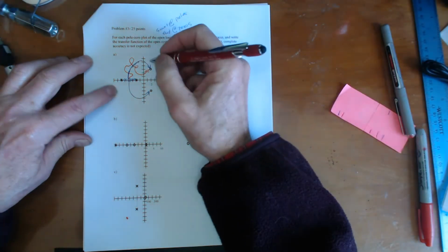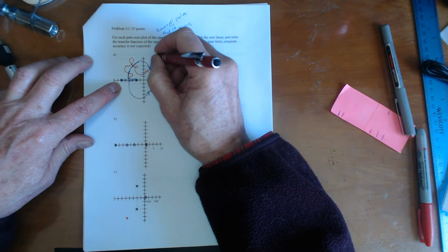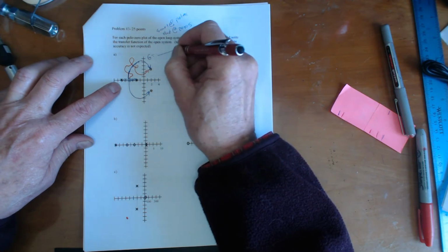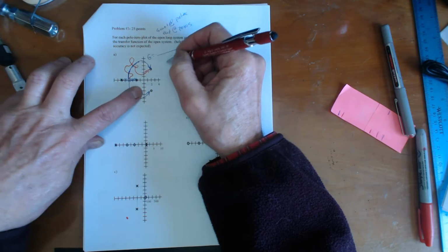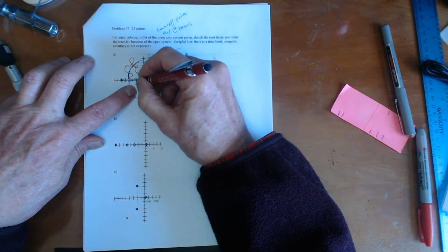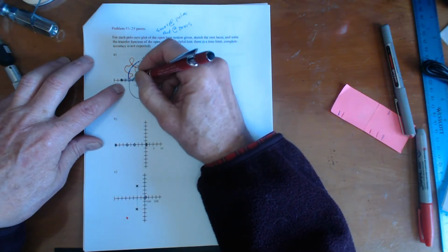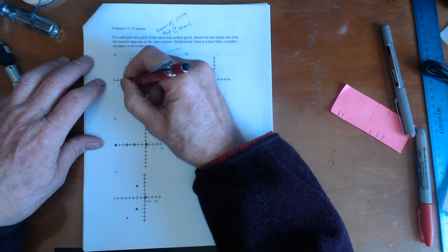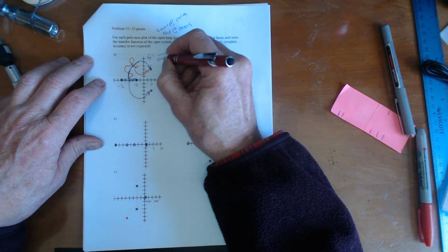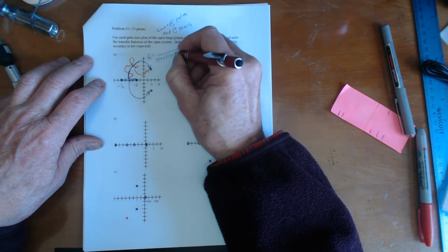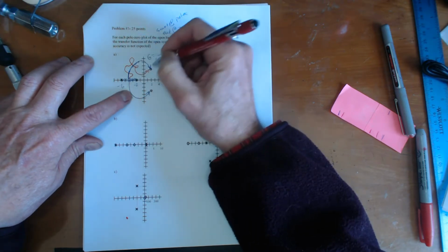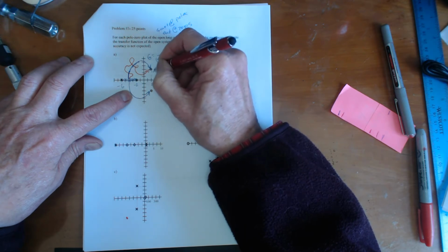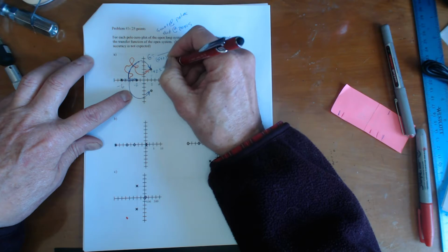Okay, so what are the roots? So what does this transfer function look like? G looks like something like this. So we have to look at what the poles are. So this is a 2, minus 2. Let's see, 1, 2, 3, 4, 5, 6, and minus 6. So this is S plus 2, S plus 6. This one's a little harder. So this one is 2. This is plus 2 plus or minus 3i.